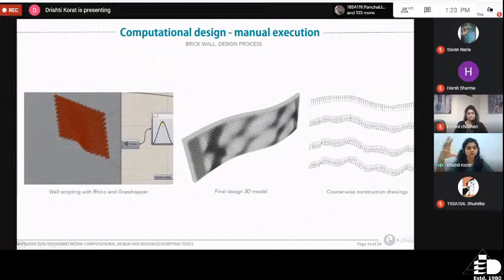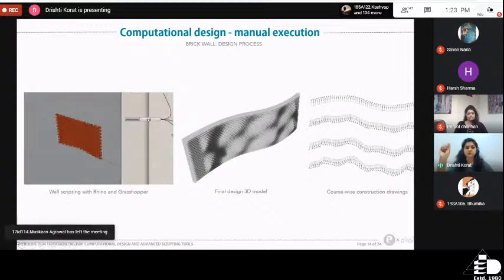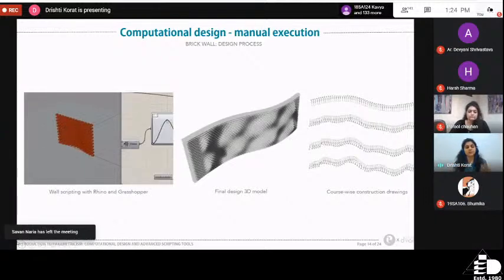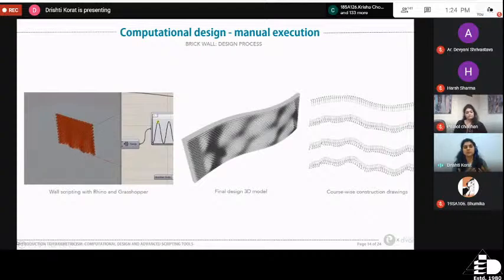Or when, for example, I reduce the curvature, I could reduce the number of curves, or increase them. So I'm changing those parameters. I could also change the length of the wall or change the spaces between those walls. All of these aspects become my parameters, and when I change them, I can see the result in my final design. So we started off by scripting the design in Grasshopper and seeing its